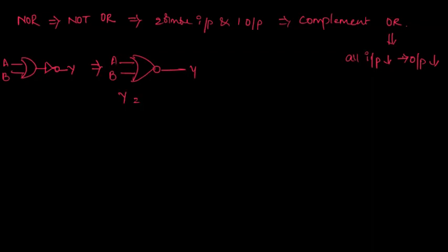The expression for NOR gate is (A plus B) whole bar, where A plus B or A or B refers to OR function and it is a complement, so the bar. Okay, now let us realize its truth table. Since we have two variables, there are four combinations. So except in this case, that means here it is high, remaining all it is low. So this is how NOR gate is realized.